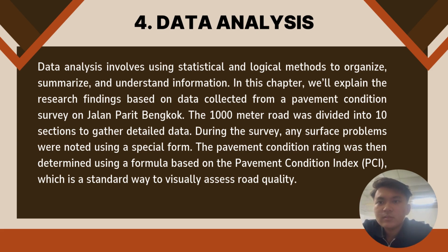Assalamualaikum. My name is Daniel Aiman bin Zamzuri, matrix number DF240040. I will be presenting the data analysis conducted for our pavement condition survey at Jalan Parit Bengkok. The data analysis involves using statistical and logical methods to organize, summarize and interpret the data we collected. We focus on a 1 km stretch of road, which is divided into 10 equal sections, 100 meters for each section. Each section was carefully surveyed for surface defects using a specific form.